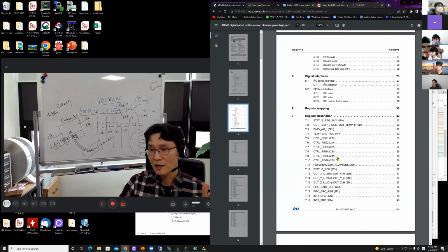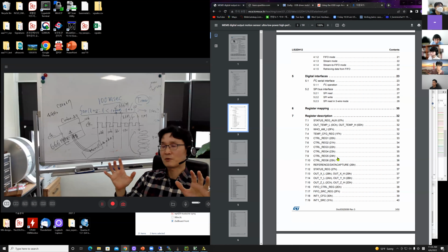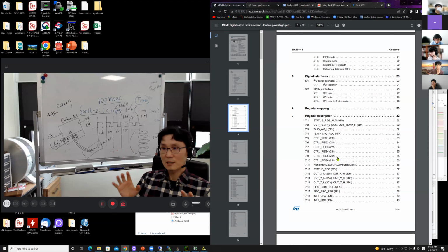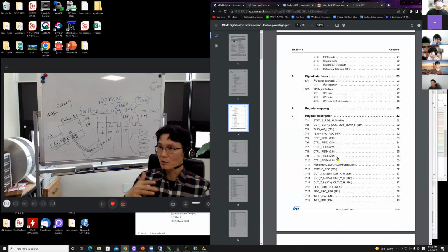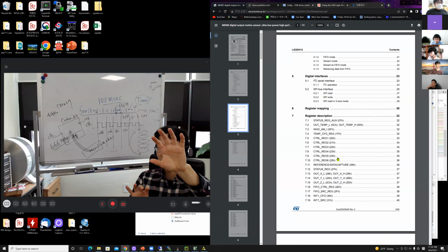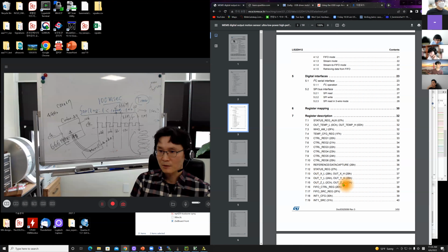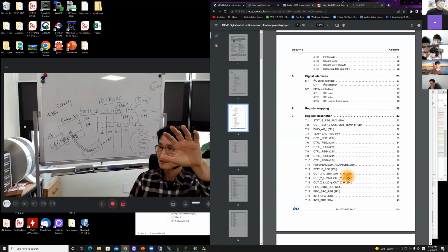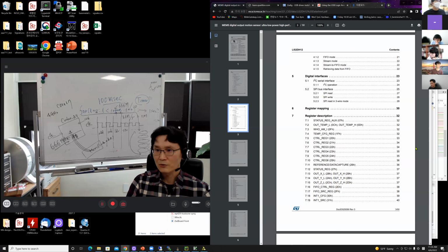So every I/O device, right? Think about I/O device. Before you use an I/O device, you have to set configuration. That is too obvious, right? You have to set the operating condition. Then normal operation. During normal operation, this hardware is recording its status. So three different registers: configuration registers, data registers, and status registers. So that's what you have to present.